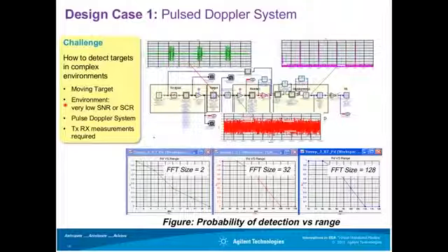And also, we plot the input waveform as can be seen here. In time domain, since the signal-to-noise ratio is very low, signal-to-clutter ratio is very low, the target is just hidden. You have no way to extract the target in time domain.